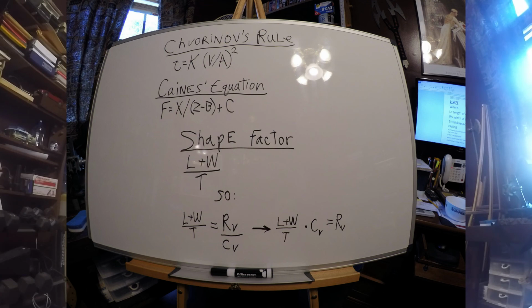It's general knowledge that the best shape of a riser is a cylindrical shape, for obvious reasons, you would be drawing too much molten metal into the riser itself if it was any other shape. So a cylindrical riser needs to be used, but how do you determine how big the riser is going to be? How do you design the riser? Well, this one mathematician made up Chvorinov's rule.